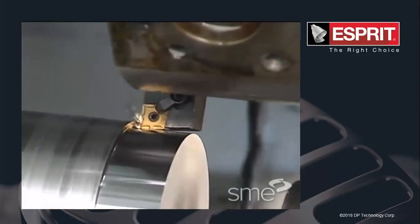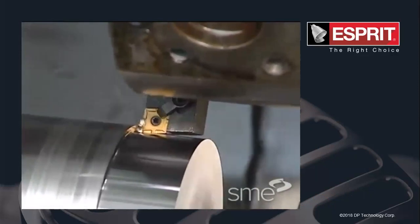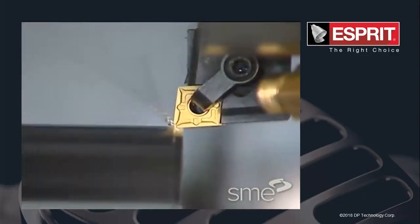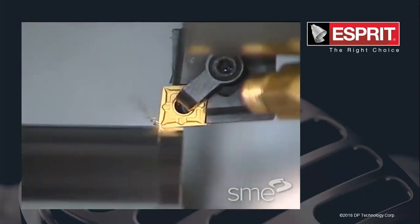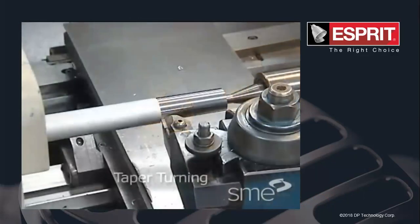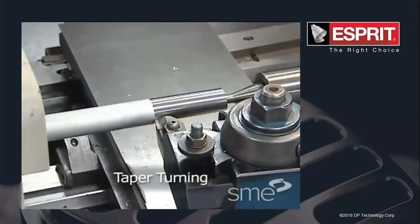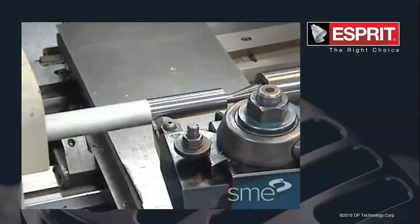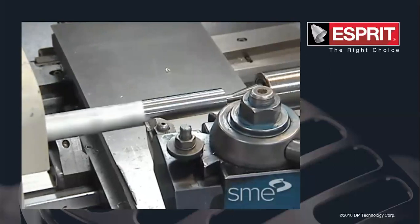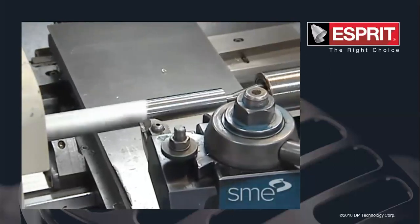Rough turning and smooth turning: when the depth of metal to be cut is more, we call it rough turning. When the final finishing has to be done, we call it smooth turning, using various carbide tools. This is taper turning, which can be done through the compound rest or by setting over the tailstock. All of this comes under turning operations.